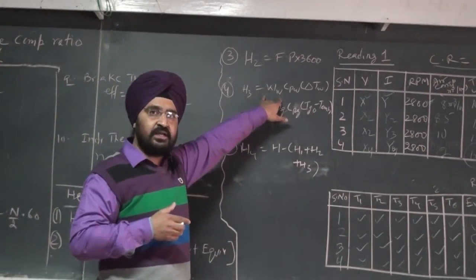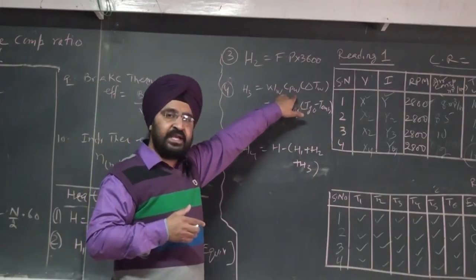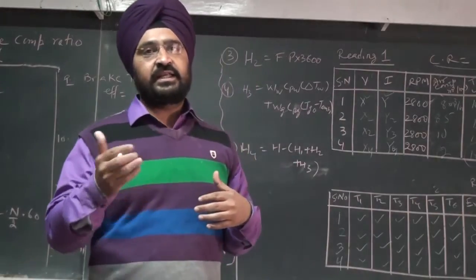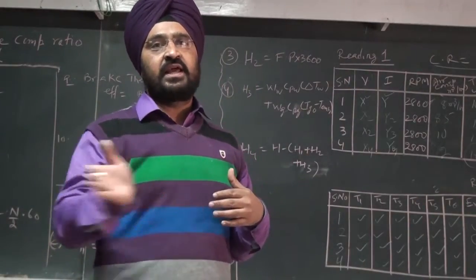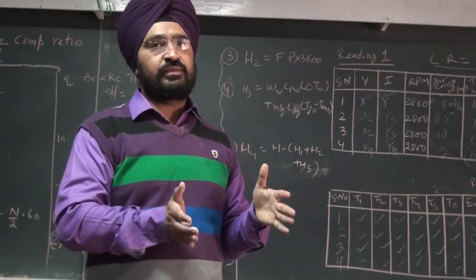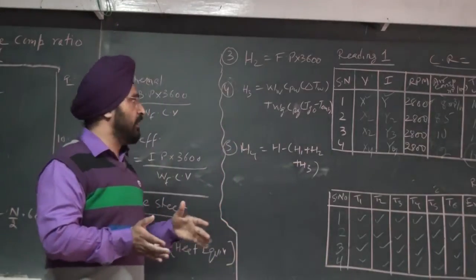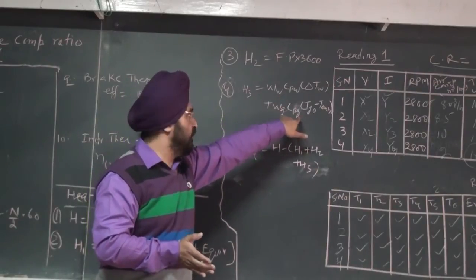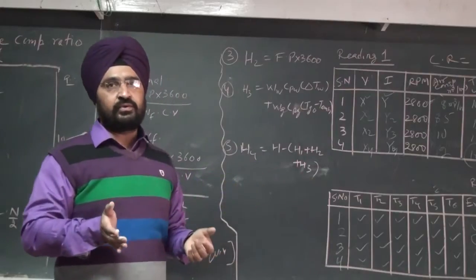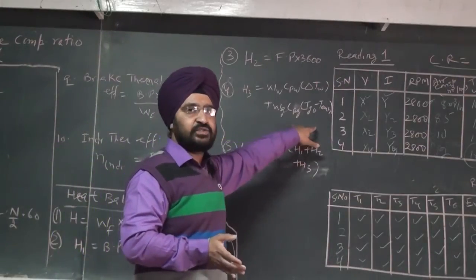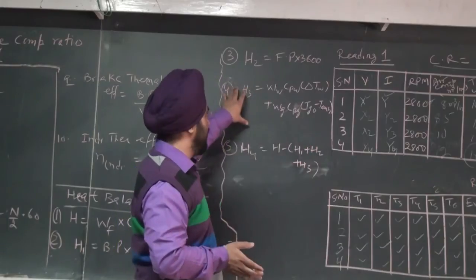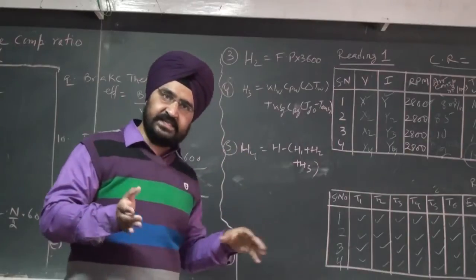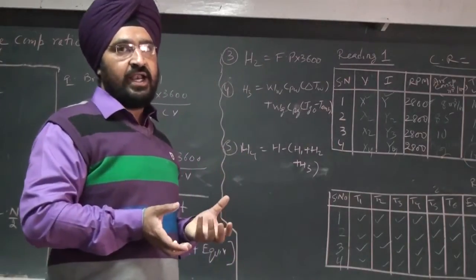The mass of the cooling water required for the engine, into CPW 4.18, into the delta T, the difference between the temperature of the water entering the engine and exiting. We get that information from the panel and have noted it down in the table. Second, the amount of the gases into the CPG, maybe 1.12, and then into the delta T, which is also measured. Then we calculate the amount of heat carried by the gases, and finally how much heat is accounted for as unaccounted losses.